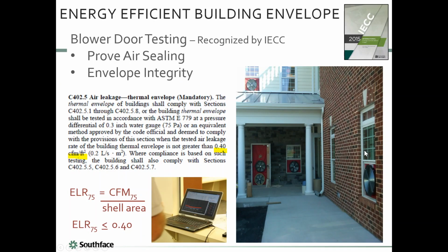This is kind of cool. One thing I do like about the IECC is they actually acknowledge the option of blower door testing to prove airtightness. And this is something that we absolutely advocate for. It's going to make it into ASHRAE in the next iteration, but it's not in this iteration. But it's an option to prove air sealing. We think it's really valuable.